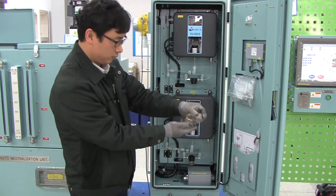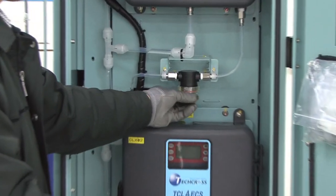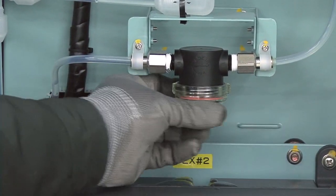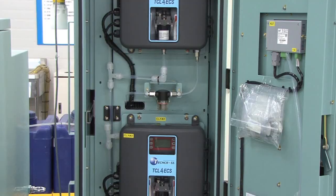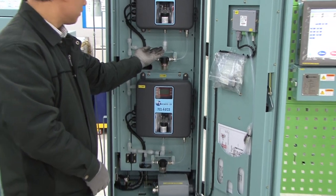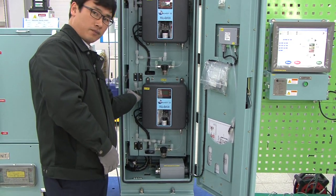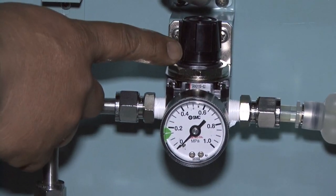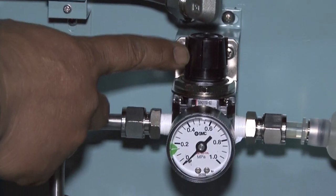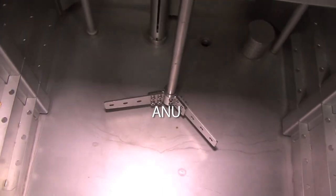Step 3. Reassemble the filter, following instructions in reverse order from Step 2 to Step 1. Step 4. Check all pipe connections and valves for leaks. 1-2. Adjusting pressure level of regulator. Step 1. Set pressure level of regulator on the right side of circulating pump to 1.5 bar by adjusting dial of regulator.